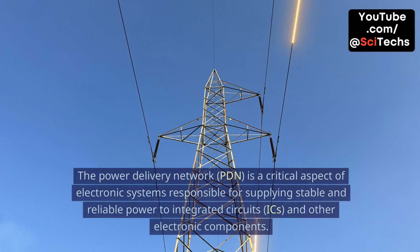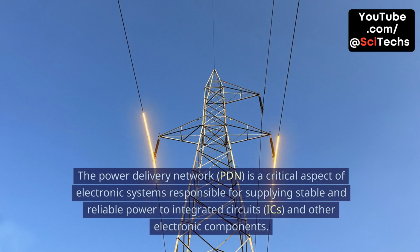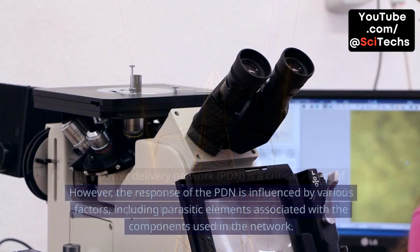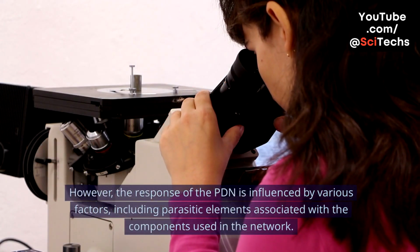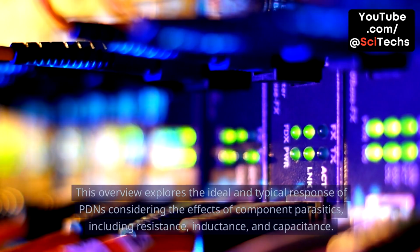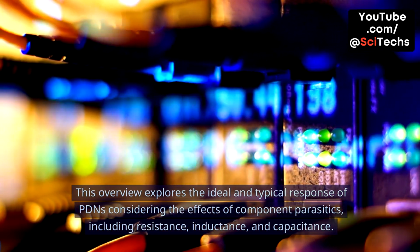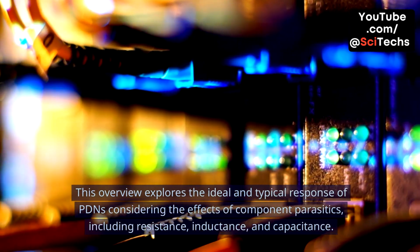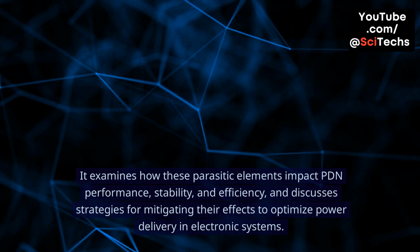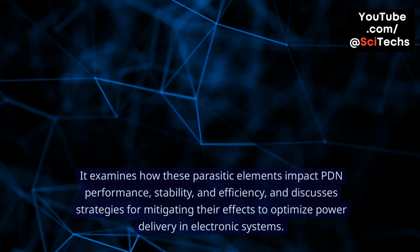Introduction. The power delivery network, PDN, is a critical aspect of electronic systems responsible for supplying stable and reliable power to integrated circuits, ICs, and other electronic components. However, the response of the PDN is influenced by various factors, including parasitic elements associated with the components used in the network. This overview explores the ideal and typical response of PDNs considering the effects of component parasitics, including resistance, inductance, and capacitance. It examines how these parasitic elements impact PDN performance, stability, and efficiency, and discusses strategies for mitigating their effects to optimize power delivery in electronic systems.